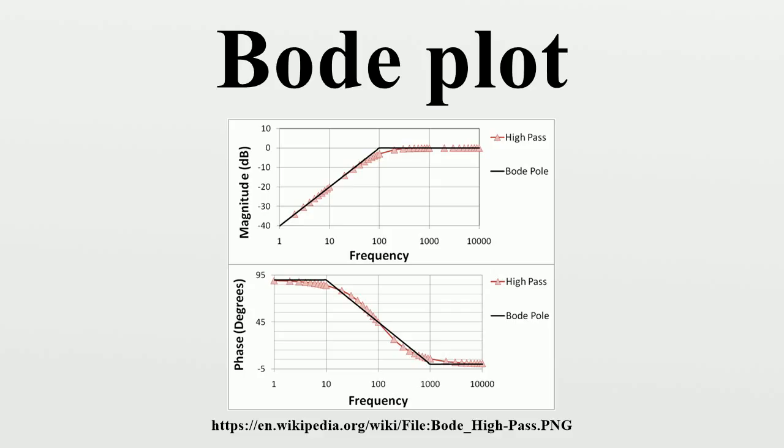For many practical problems, the detailed Bode plots can be approximated with straight-line segments that are asymptotes of the precise response. The effect of each of the terms of a multiple-element transfer function can be approximated by a set of straight lines on a Bode plot. This allows a graphical solution of the overall frequency response function.